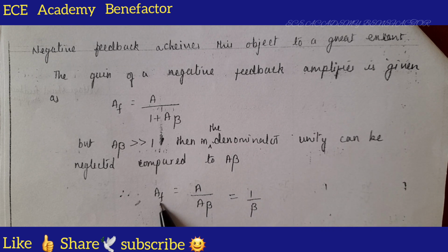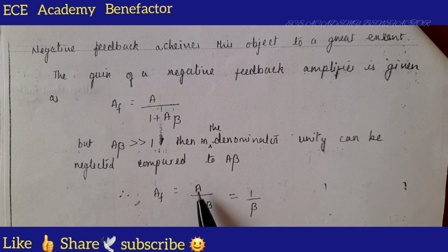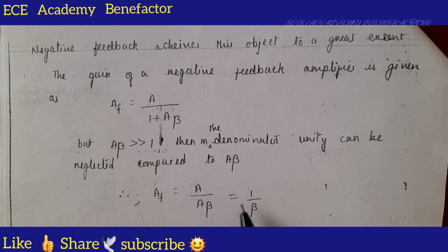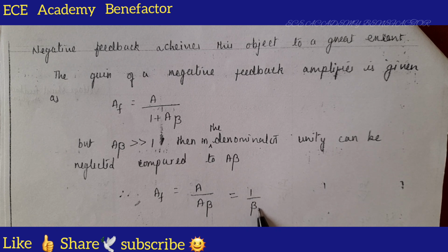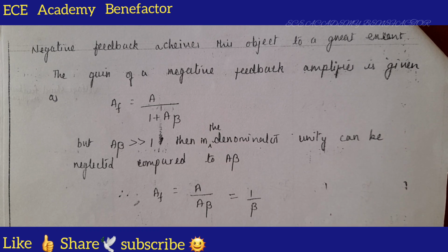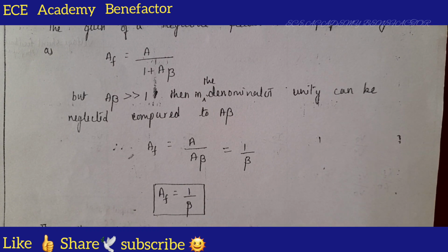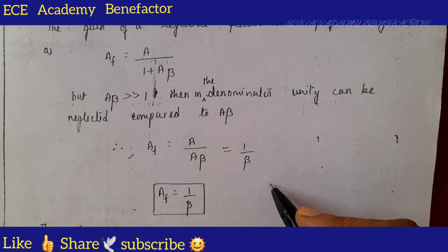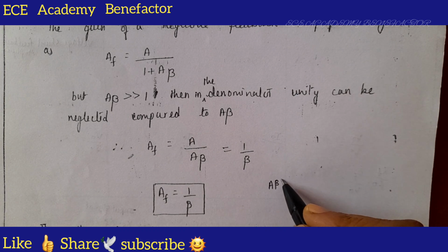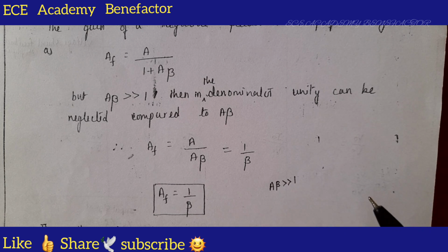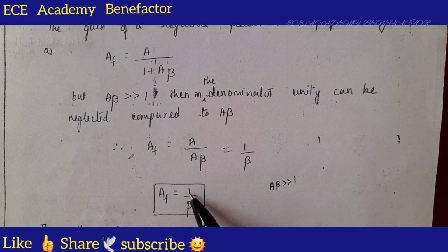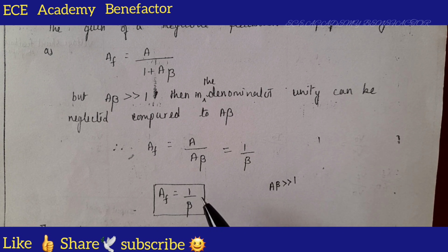Now this gain with feedback, that is with negative feedback, is no more depending on gain. It is purely depending on beta. What is beta? It is a feedback ratio. It is based on a few passive elements like resistors. So one way of stabilizing the gain is by making the A beta value very large compared to 1, so that AF becomes independent of A and depends only on beta. And resistor means it's a passive element, so there will not be much fluctuation and the gain will be stable.